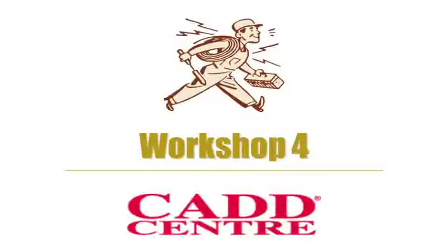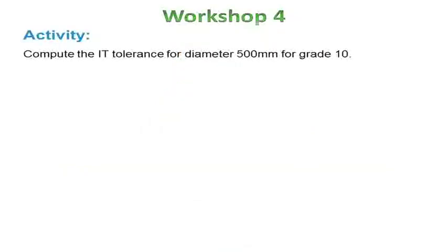Now, you have to complete workshop number 4. In this workshop, you have to calculate the IT tolerance for an object which is having a diameter of 500 mm for the IT grade 10. Once you complete this workshop, you can verify the results with the completed results which is available in the ORG page.